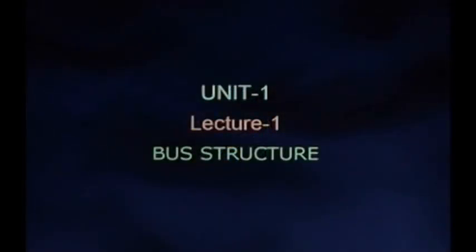Before we go into the details of the bus structure, let us briefly understand the function of each of the registers that are present. The input register is used to input data from peripheral input devices into the computer. It is basically a shift register of appropriate word length, generally 8 or 16 bits, which has a facility of parallel loading and serial shift.